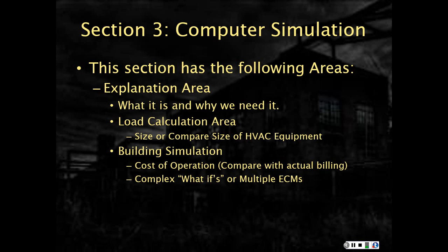The next major paragraph is describing what a load calculation is. In essence, we want to get across to the reader that it's meant to size the HVAC equipment. In a new building, this would be used to actually do the selection. In an existing building where we're doing an energy audit, this is done so we can take what the carrier program is predicting should be the size of the equipment with what's actually in the building.